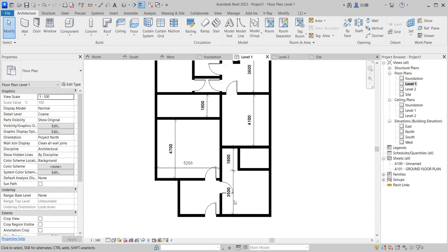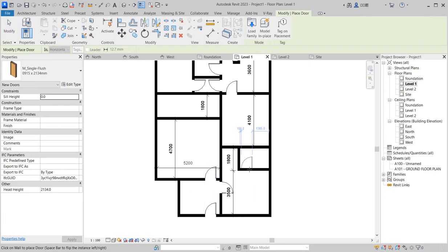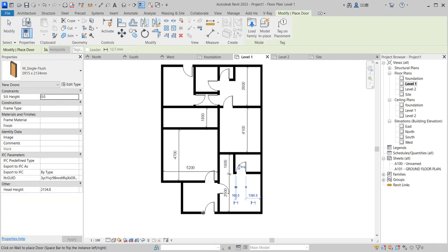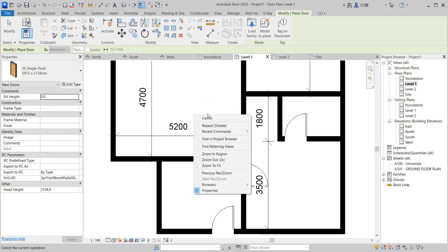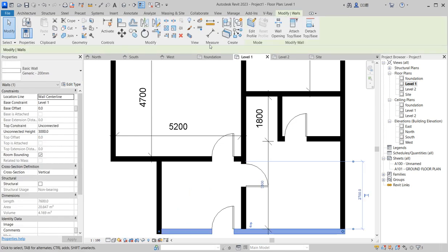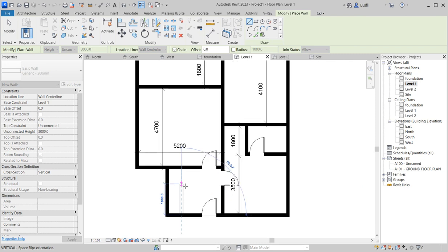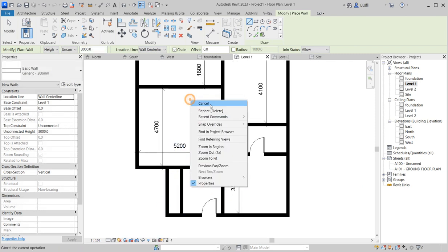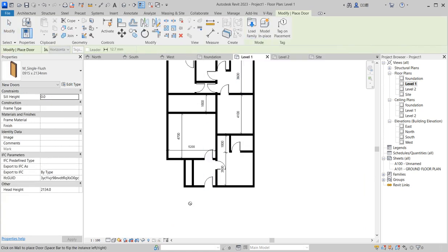So as I've done with this one now, which is the whole space that I've programmed, let me clip this one a bit. What I'm going to do is that I don't have a visitor toilet at the ground floor, so I'm going to create that visitor toilet immediately now. So create this one, right click the visitor, create this one and separate this one from the origin. So click it to finish. So what are you doing? You pick this door and say pick host or create similar.